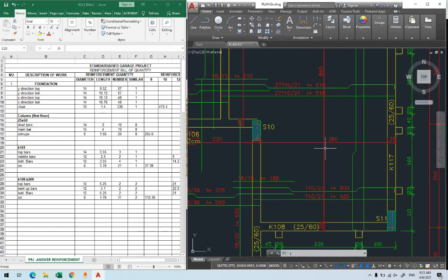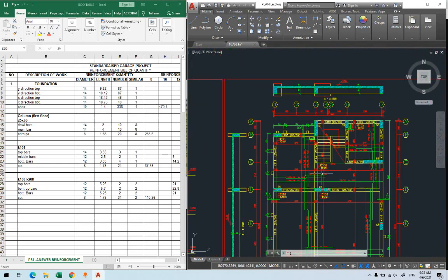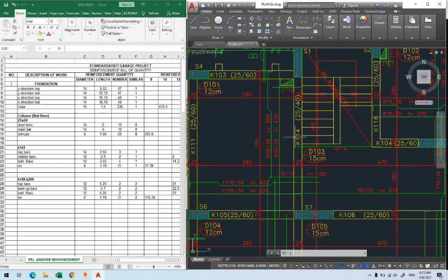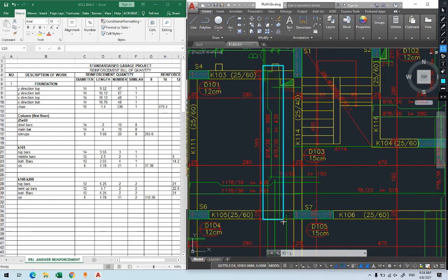So the X direction, the Y direction, yes. Each slab has two directions as well. For example, this slab, I have it here. I can take the reinforcement out if it is too crowded for you to see, but I'll highlight it for you. This is the other direction, which means that you're looking at the slab in this way. So what we have is the bottom of it. This is the bottom bar. And this is the bent up bar that we have. So you have the bottom and the bent up bar there.